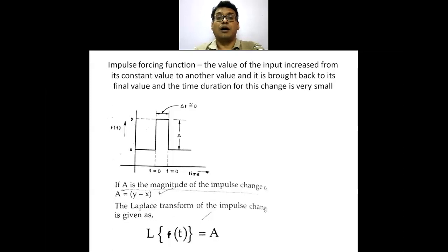That means a control valve is manually opened by mistake, or by use of a controller it is opened, and then suddenly it is closed, understanding that this should not be done. So that is why it has been closed. However, if the reactions are exothermic and producing very high heat, then at that time this small mistake can also cause damage to the process.